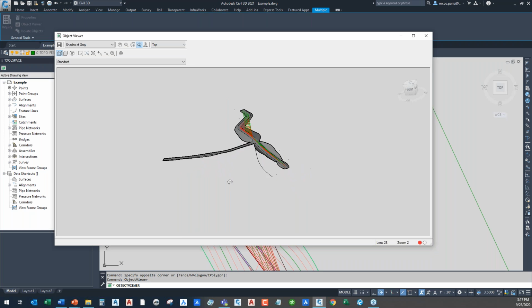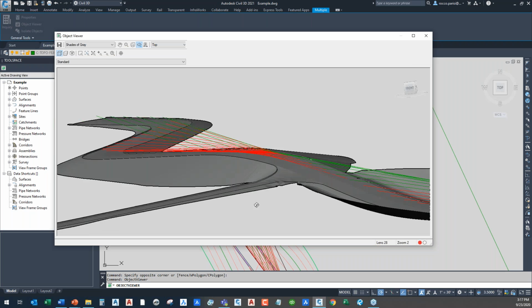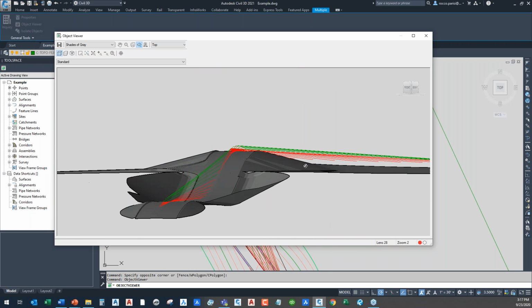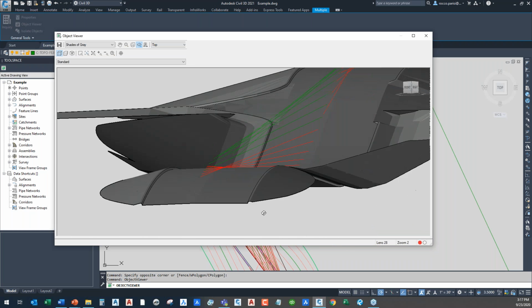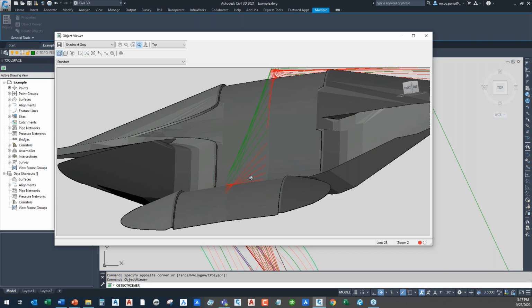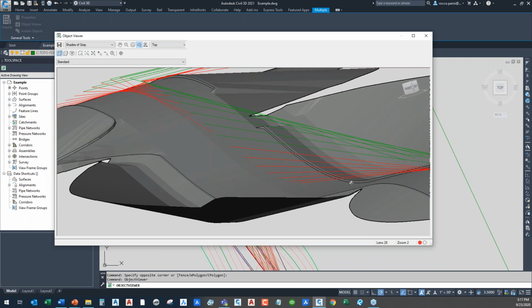So as I go in and tilt up, you see that those are actually up here, so you can begin to see from a visualization point. You can turn and actually follow the road and say, oh, I see what's happening. At this point you can see, just move to where you want to be, here you can see this is all blocked. That's blocking my vision. By following the road, I can see traffic moving up the hill there with no problem. I can see up to there, but down here below in the dip, my visualization is going to be blocked. I'm going to miss traffic as I'm coming over this hill. I'm not going to see cars that are in that dip right here.